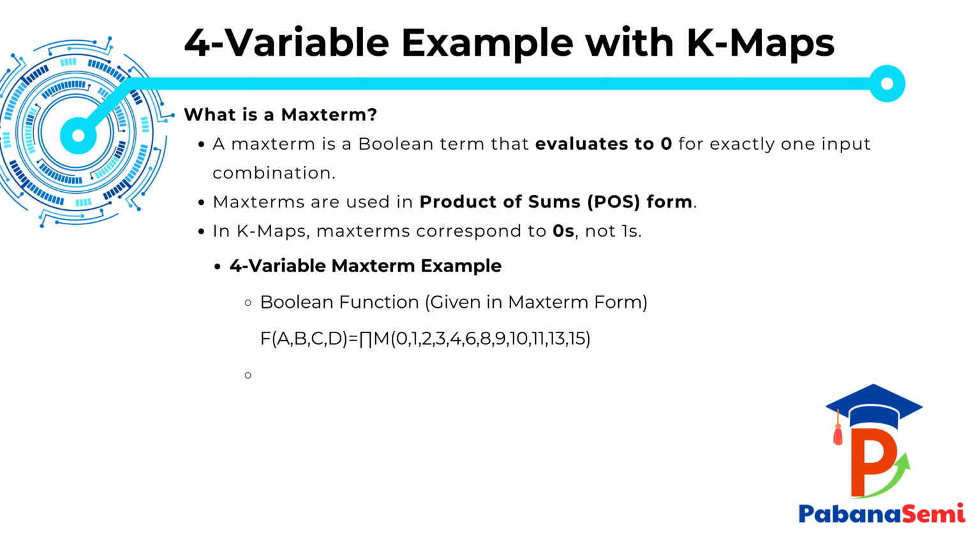In the K-map, we shall place zeros at these max term locations. Then, we will group the zeros to derive the simplified POS expression. This marks the conclusion of our introduction to max terms and sets the stage for K-map grouping in POS form.